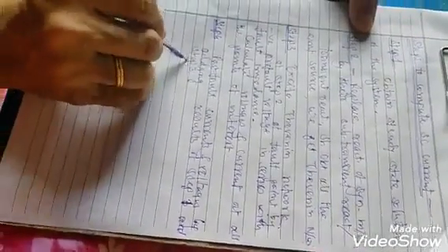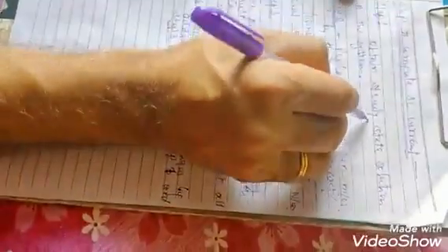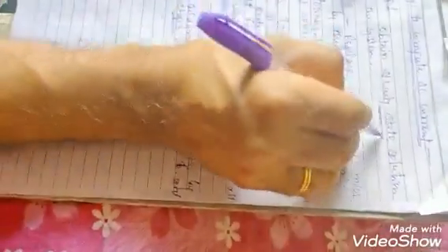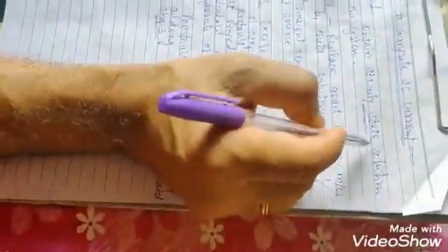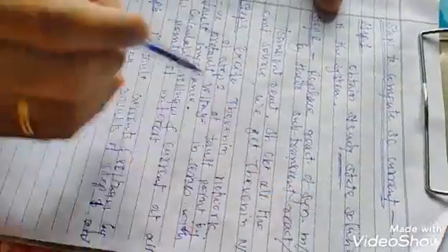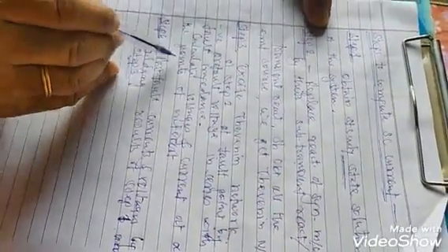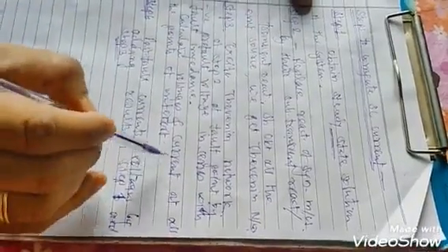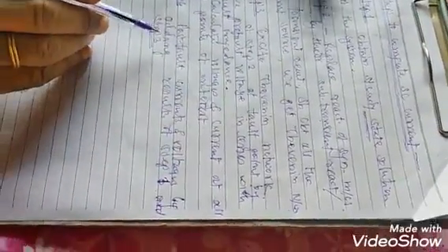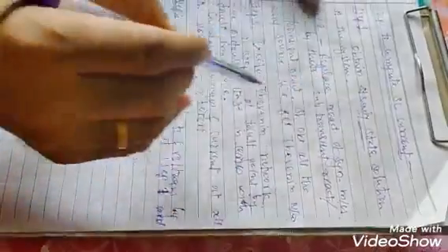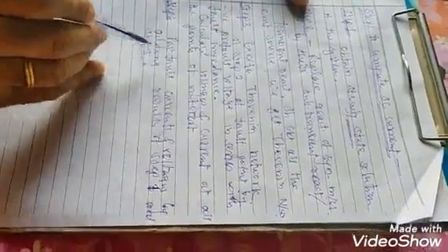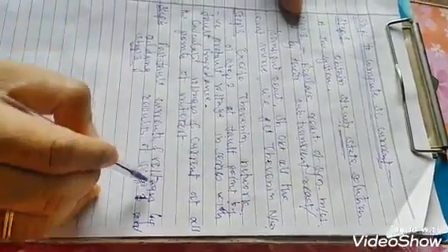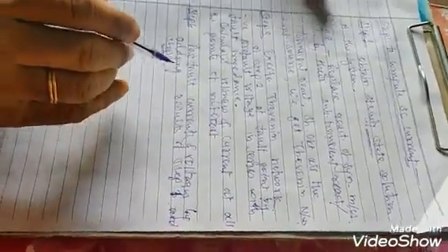So in step 1 we are calculating currents and voltages at steady state condition, and in step number 3 we are calculating the voltages and currents at the fault point. Then this current is added with this, and we get the post fault currents and voltages.